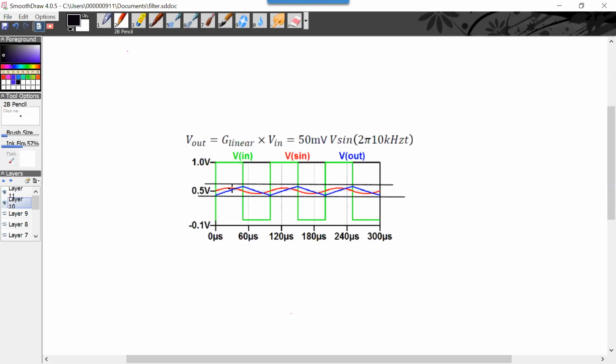I've drawn this ripple a little larger, but inside here it's rippling. So you're uncertain about the voltage inside that ripple. The way I've drawn it, that uncertainty divided into the whole voltage range is how many bits you would have.